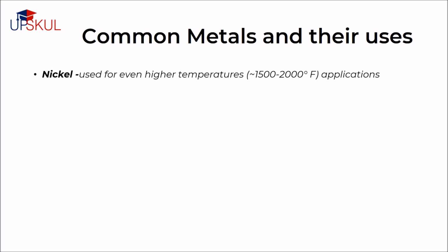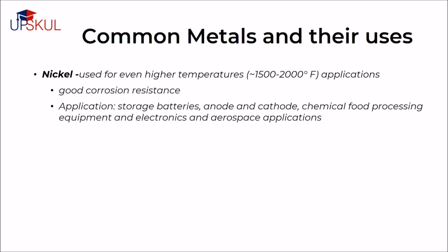Nickel alloys are used for even higher temperatures between 1500 to 2000 degrees Fahrenheit with good corrosion resistance in storage batteries, anode and cathode, chemical and food processing equipment, and electronic and aerospace applications.